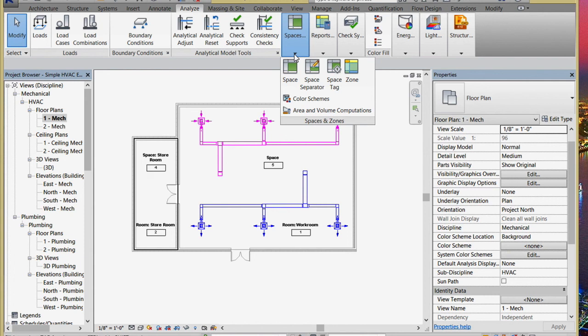In some buildings, you could have every space have its own separate zone with its own separate thermostat. This building tends to have that. We have these separate thermostats in each individual room. But if you want a collection of spaces that are all tied together on a single thermostat, then you make a zone out of them. So in terms of zones, let's take a look at that.